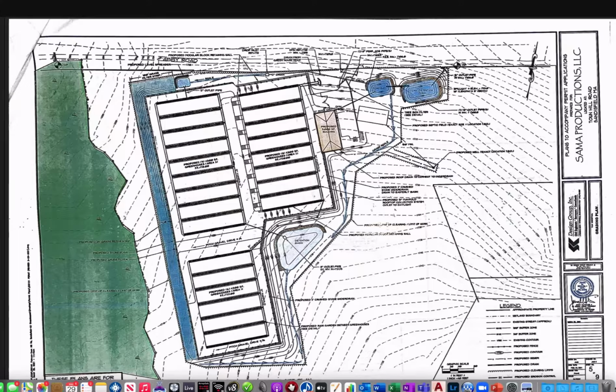The site as it lays out is located near a town hill, if you look at a map. And so with that said, as you move this facility south, you're required to either step up that hill or cut into it. So I drew this plan maybe 4 times trying to figure out the grading, which is pretty typical. That's how engineers work, it's a little trial and error there. But this kind of fits. This is what fit best out of the efforts made to avoid gross excavation. Because as you go further south, the limit of clearing beyond the facility starts to grow exponentially, right? So you get this big long slope with a lot of trees removed.